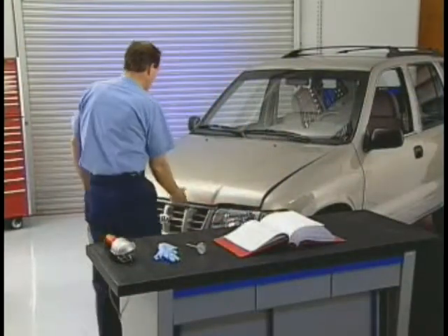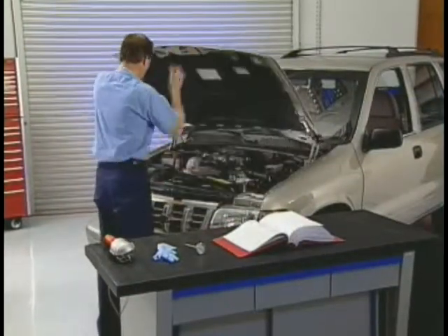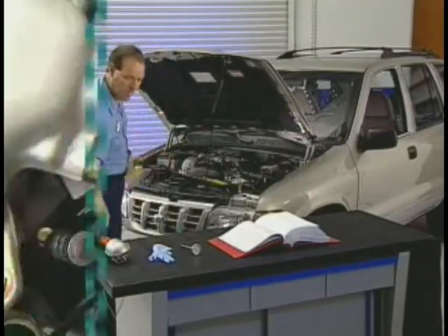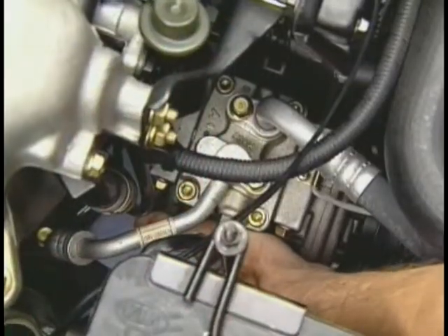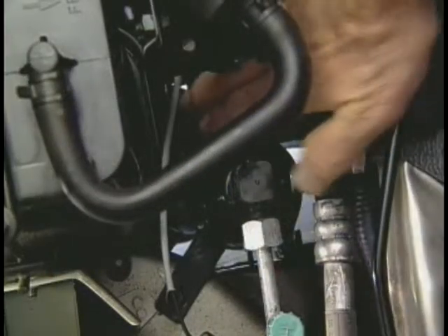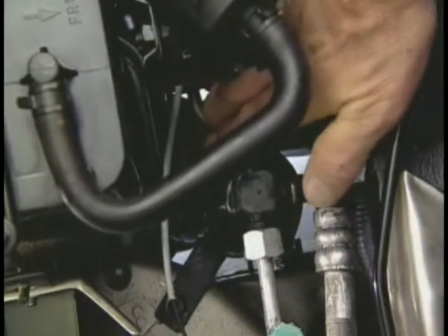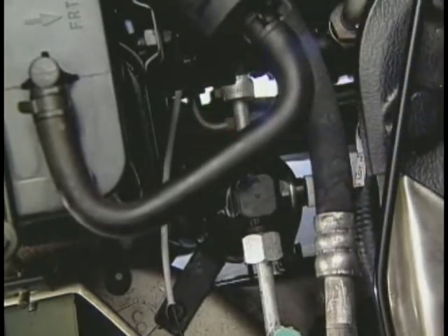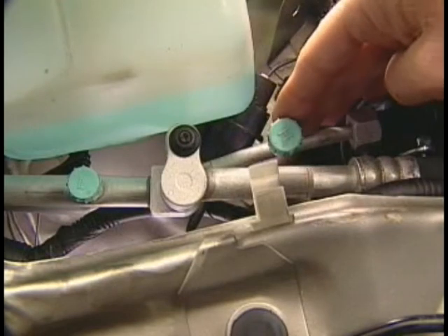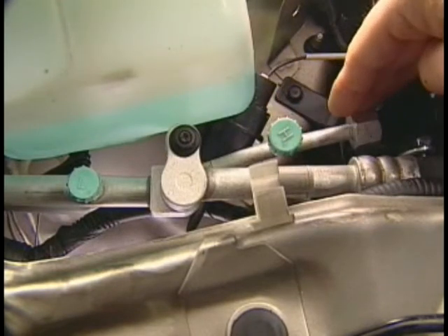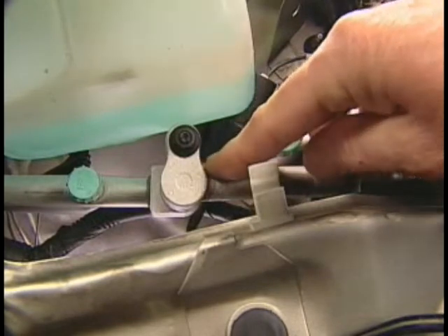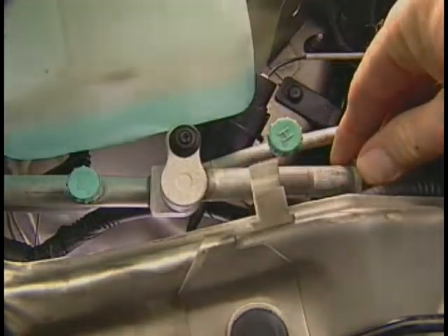A touch and feel test is a quick and easy diagnostic test to determine possible problems in the refrigerant loop. Be sure to exercise extreme caution when touching high side components as they can be very hot. Look for warm lines and components that are cold. Restrictions on the high side will have the same effect as an expansion valve or orifice tube, as they will cause a lower pressure after the restriction and cause cool or cold lines.